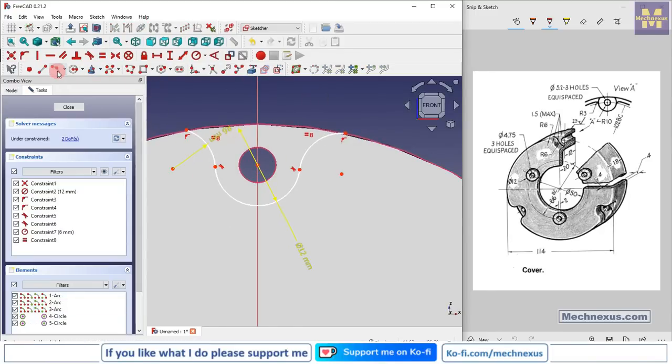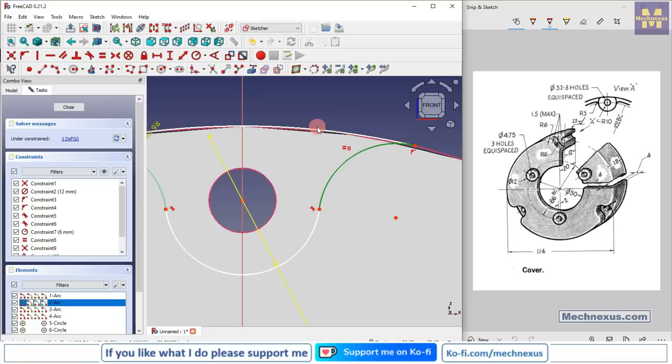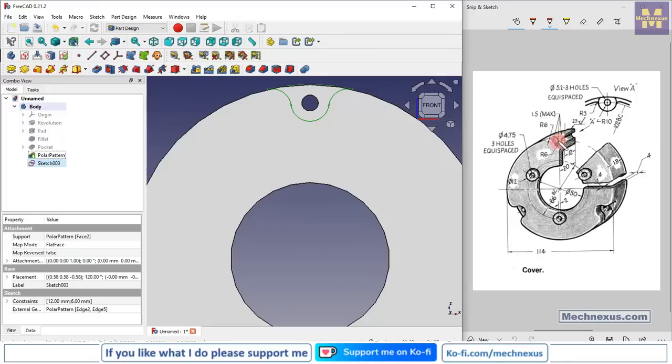And now we will close this profile with a 3-point arc, and now we will see what is unconstrained. So here we will select this and add a tangency, similarly this and add a tangency. So now our profile is fully constrained, and we will create a cut of 8 mm here.